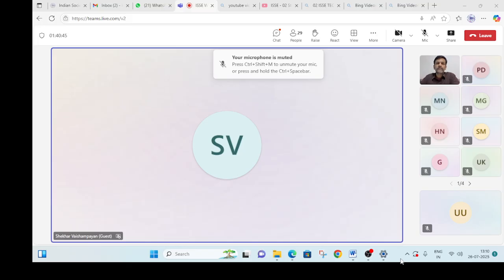Let us say you're carrying out drilling of a hole for a tunnel, for example. So this is required and it is done. When unstable formations are there, it doesn't mean that it is going to come down tomorrow. Landslides will happen, but landslides always happen when there is an accumulation of water pressure. If you can, by sensible methods, release that water pressure from location to location, the landslide problem can be alleviated largely.